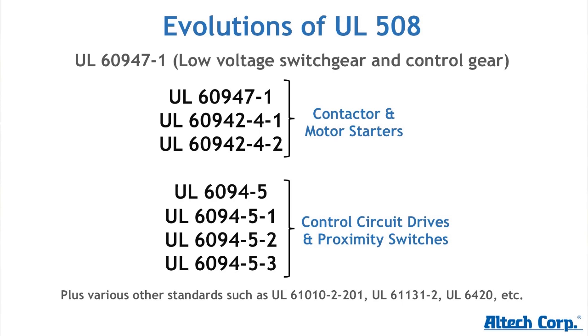But for example, you go to motor starters and go to the horsepower table, all the voltages of all the different supply systems all over the world are mentioned there. So you can get any horsepower rating for any respective voltage tested under UL, or now UL 60947.